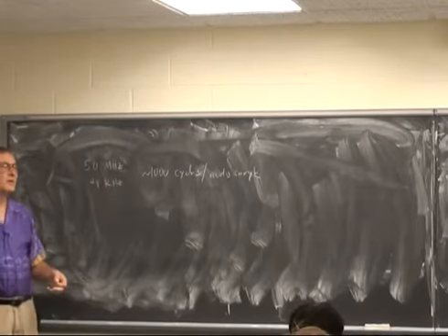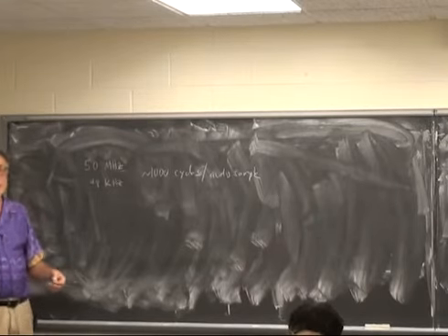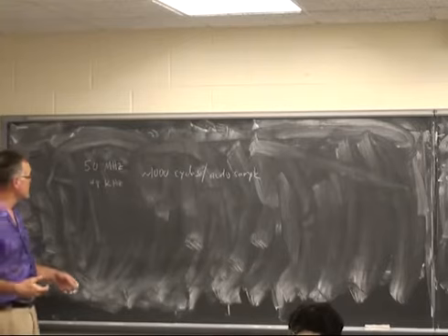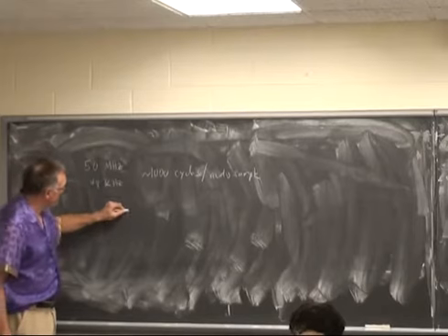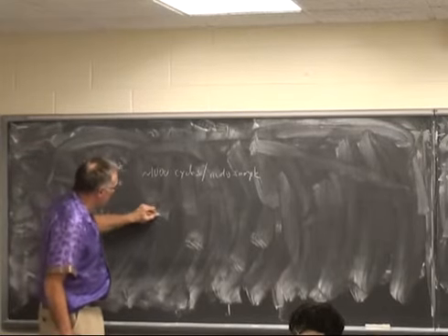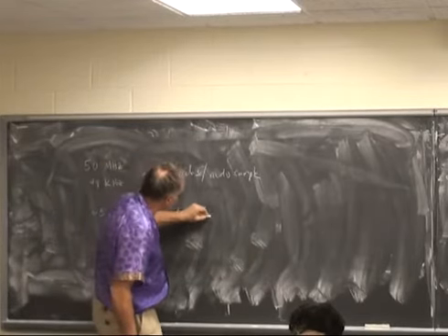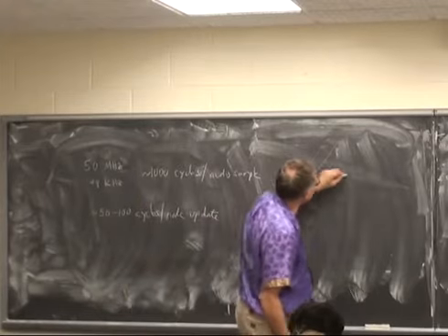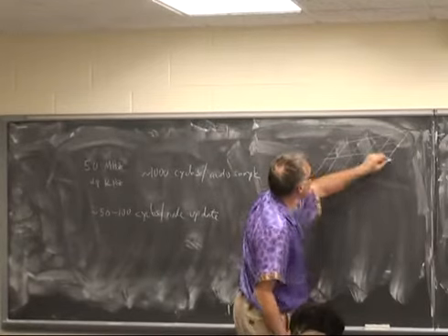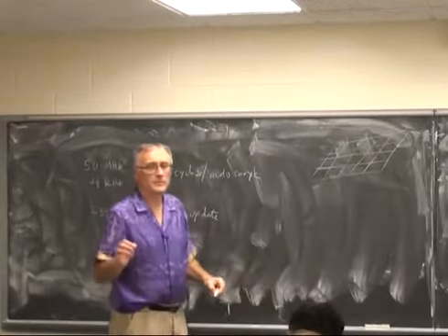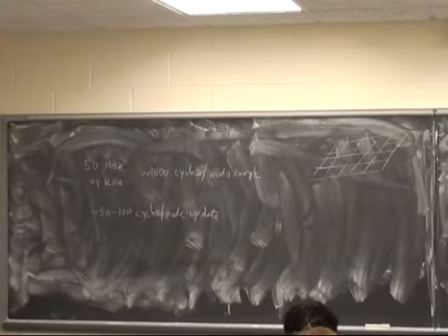By the time you retrieve from memory and store to memory and do the actual arithmetic and scale stuff, I would say we're probably talking about 50 to 100 cycles per node update, where a node is one of the points on the drum head that we talked about last time. And the spec in the lab is you have to update at least 100 nodes per audio cycle.